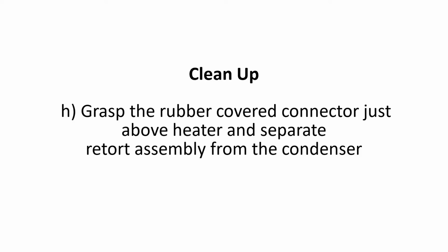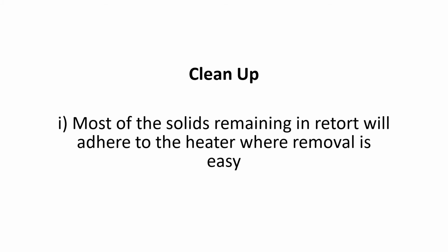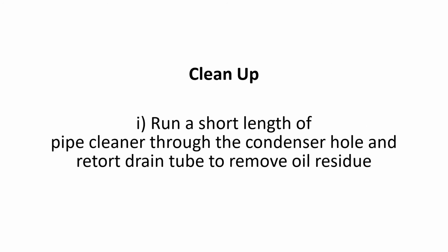H. At the end of the test, grasp the rubber-covered connector just above the heater and separate the retort assembly from the condenser. Handling the hot retort by means of the connector cord, dip in water to cool. The plug is waterproof and may be immersed completely. I. Most of the solids remaining in the retort will adhere to the heater where removal is easy. Use a spatula to scrape out the cup and expansion chamber. Run a short length of pipe cleaner through the condenser hole and retort drain tube to remove oil residue.